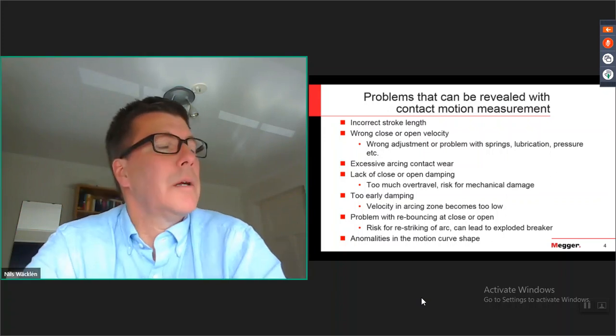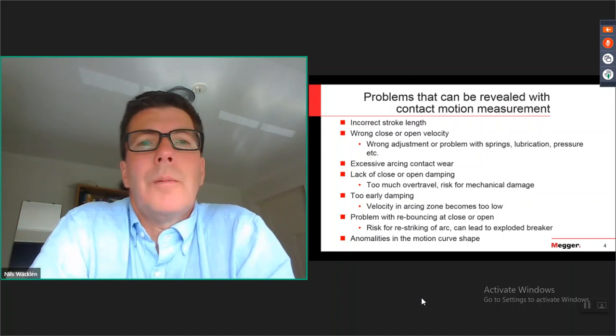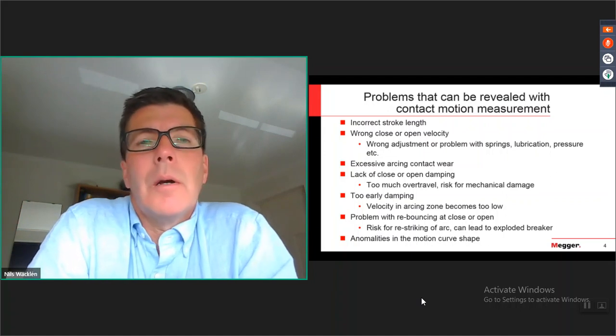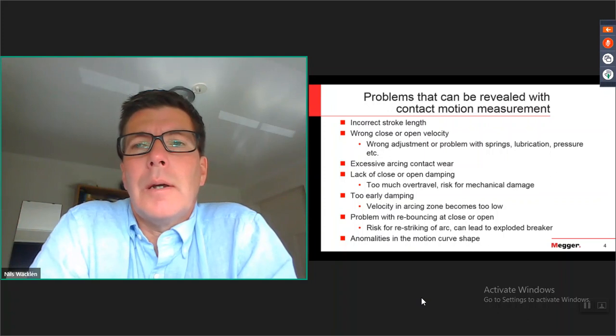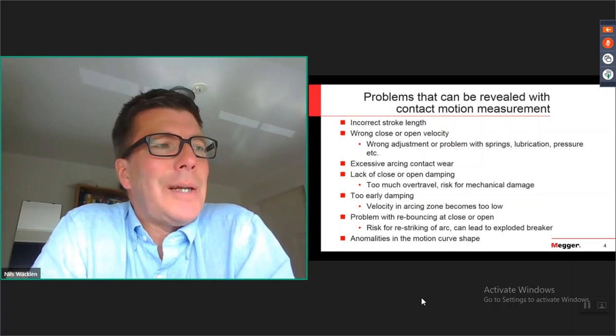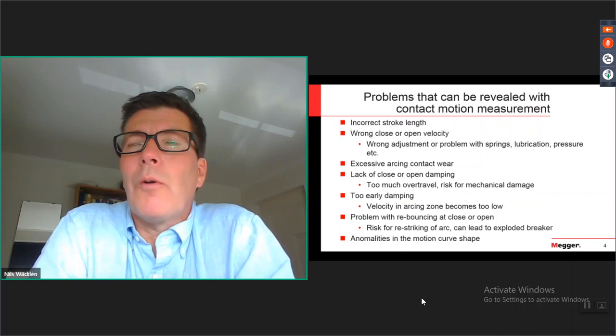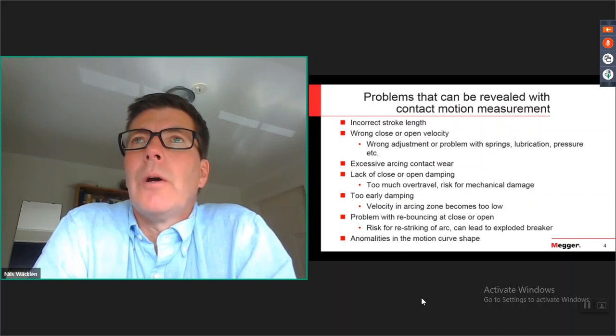Yeah, that's basically if you have some problem in your link system that it sticks in some way. You have corrosion or dried grease or whatever that makes everything need more force to move.